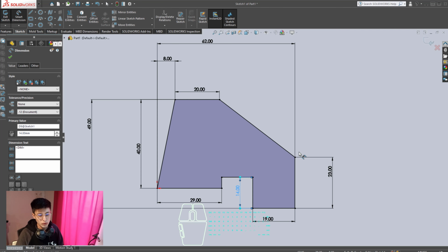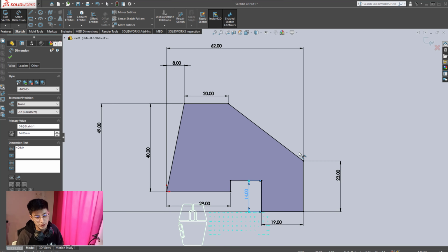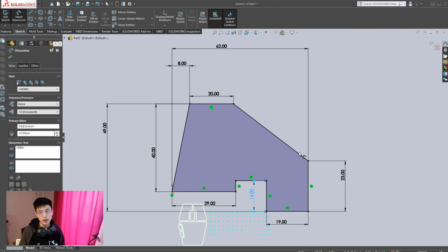All right. How do we know that this sketch has been properly defined? Basically, because of the color. If you have a sketch that still has lines in blue, that means that it is not perfectly defined. There are some lines that could be moved, and that is a mistake. Every single one of the lines has to be black for you to continue with the process.